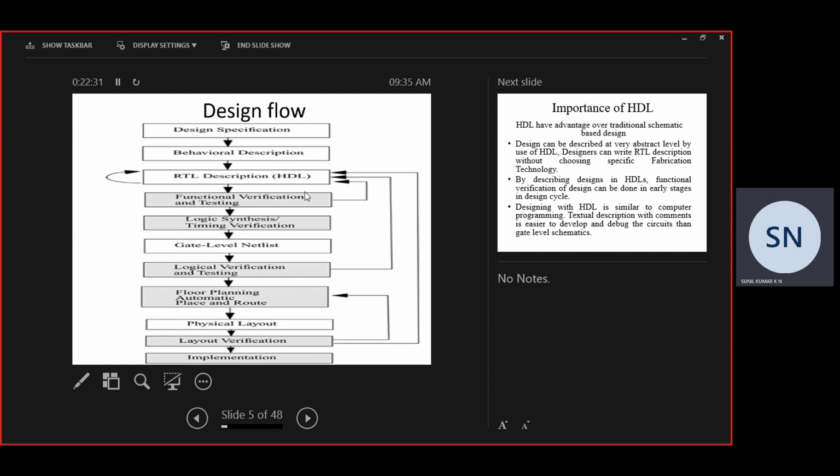So for this output, if I give the truth table, according to my truth table, suppose 0, 0. What is this? NMOS works with the positive voltage, and 0 is negative. So in terms of logic level, 0, 0 means both NMOS will be in off state. Here both PMOS will be in on state.